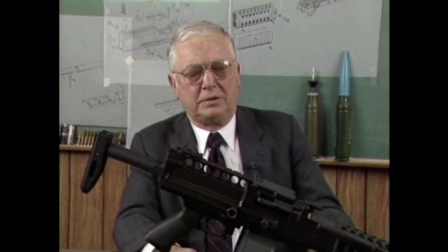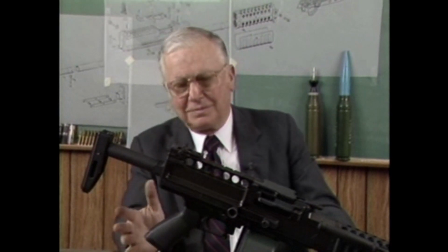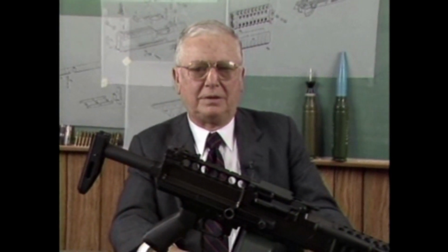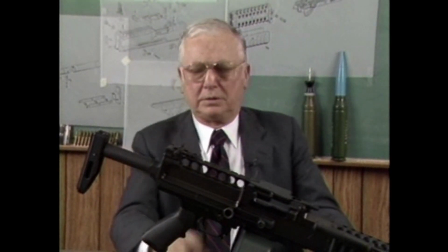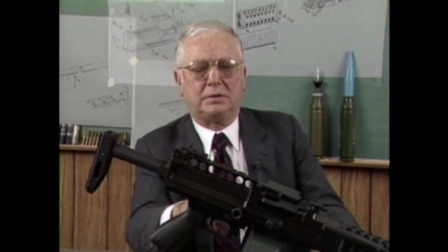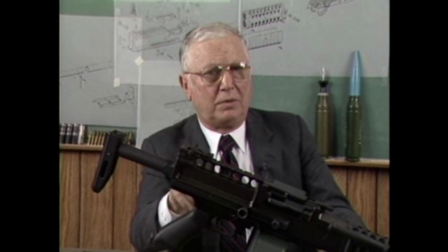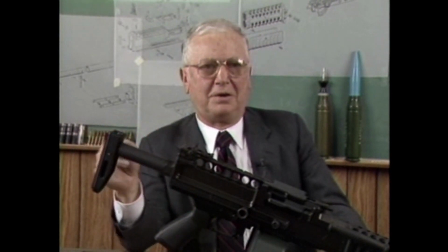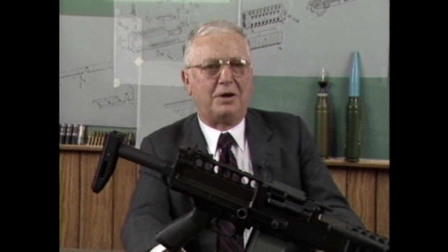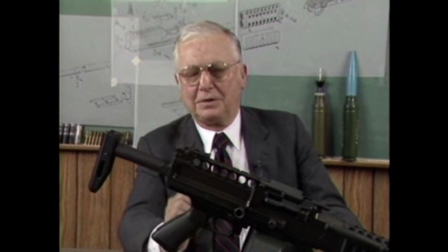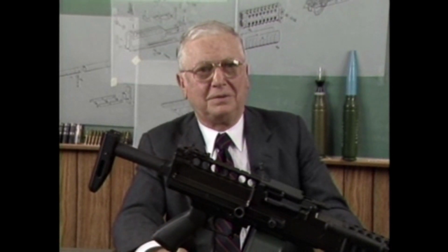But one of the things in the user that you have to worry about is inadvertent assembly problems, and whether he can break it apart easily by taking it apart or losing it. Some of the subtle things there, I didn't go into all these things in this bolt group, but for instance, there aren't any pins or anything to lose in that. Small parts, like in the M16, I learned that the firing pin retaining pin was the first thing that was lost. First field trip, they'd lose this little pin, and away it would go, and the weapon was useless.